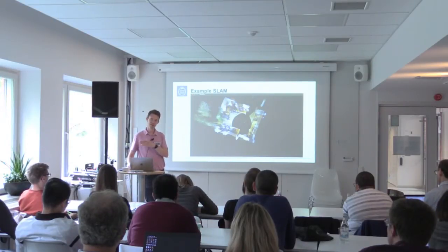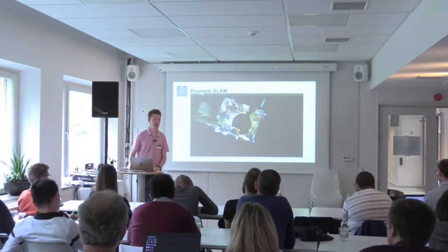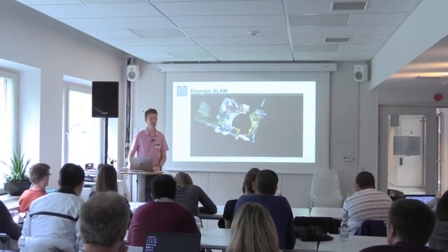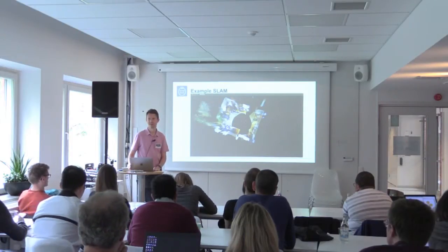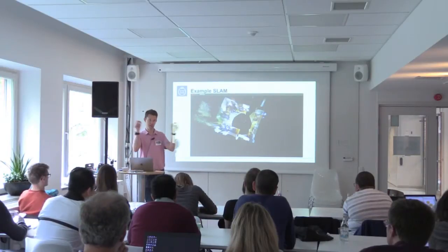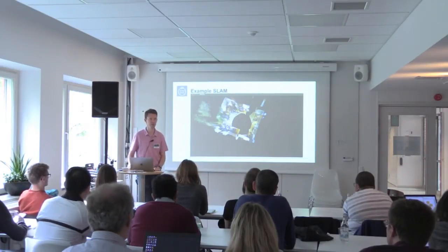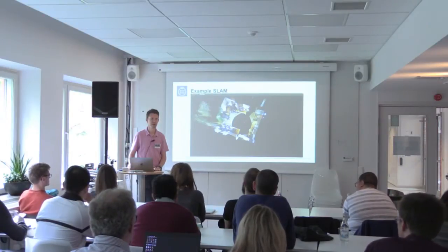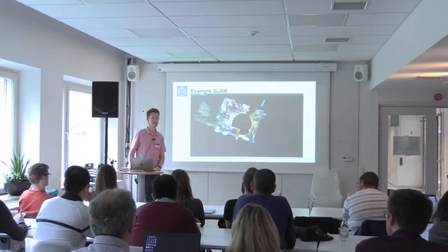So the further away, at a certain point, you will get a really drastically large error. And what's the way to reduce the error? You could fly closer, or you could put the cameras further apart. What's the problem with putting the cameras further apart? Space in the robot. It would take space, yeah.